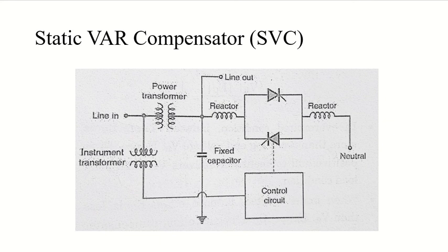If the circuit is designed to adjust the firing angle of your capacitor or reactor, with both of them connected, the unit will act as a continuously variable element in the power circuit. Using this thyristor control, the capacitor or inductor bank will be changed accordingly. So both reactor and capacitor are making adjustments based on the requirement of your system. And that's pretty much your static var compensation.